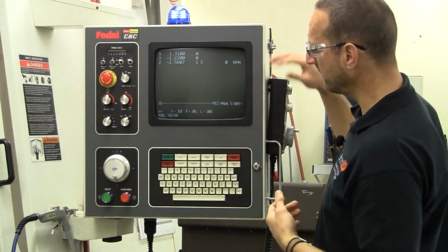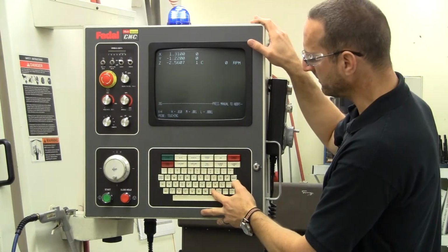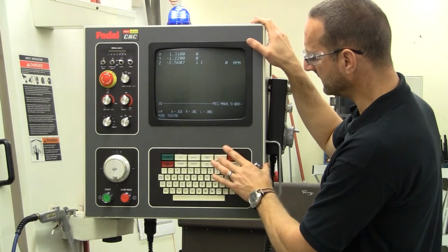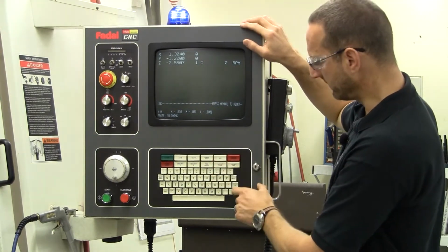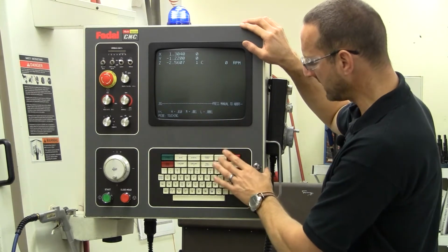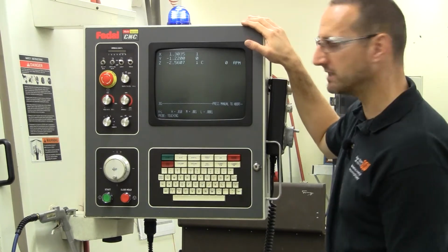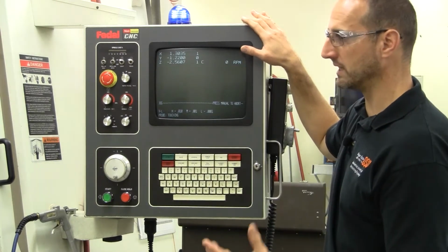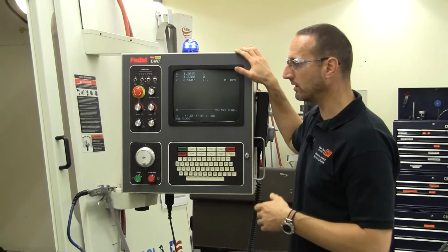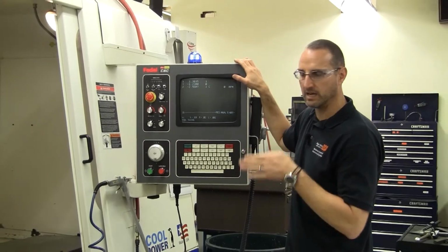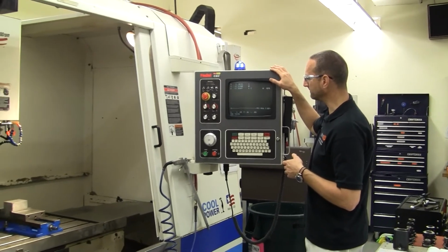Likewise, I can change my increment, so if I want to move at the 1,000th inch increment, push M, and then same thing. Now I'm moving in the thousandths place. And of course, L for 1/10,000ths, and there you go. So that's incremental jog mode, and that's very useful for doing things like touching off your tools, maybe using an edge finder to find the edge of your part. It allows you to just very finely sneak up on an edge with a tool and touch it off.